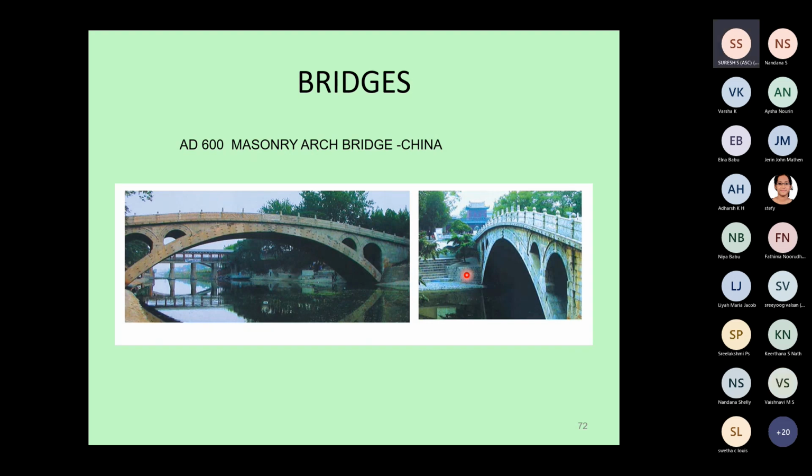Now coming to bridges. Bridges are totally different structural systems, always handling moving and dynamic loads. Dynamic loads, as we defined already, are loads whose rate of change of magnitude or direction is so fast that that rate of change will induce behavioral changes in the structure, structural behavior.